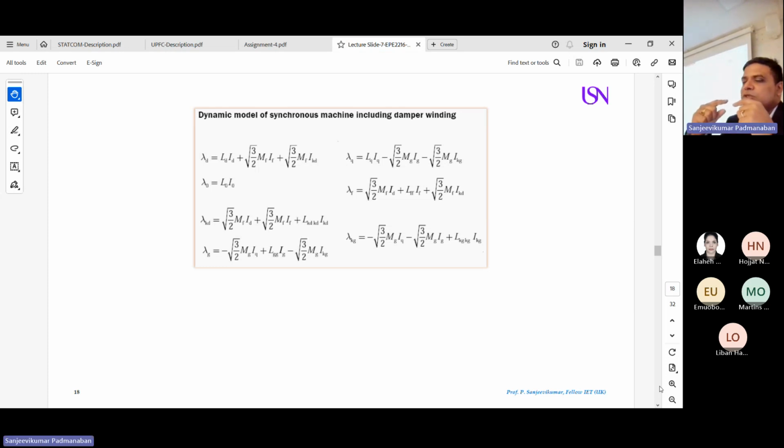But due to the small deviation of the induced EMF within your armature, it also generates some induced voltage, which is opposite to the direction of the main field. So you have a main field, say, from right to left, but the field from your armature is from left to right.